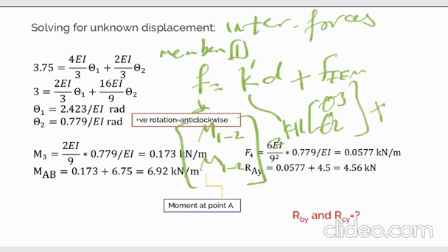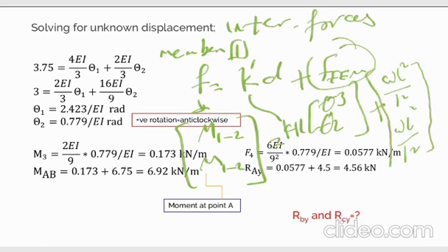You can use this one, the first step actually. So here for this one we have the fixed end moments WL squared over 12 and WL squared over 12, because here we talk about moment. This is the matrix. Then I should substitute the values.